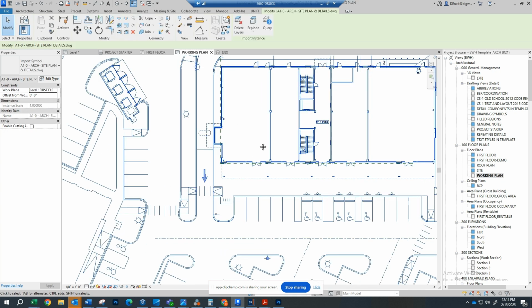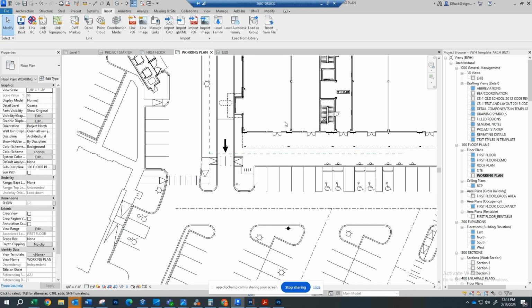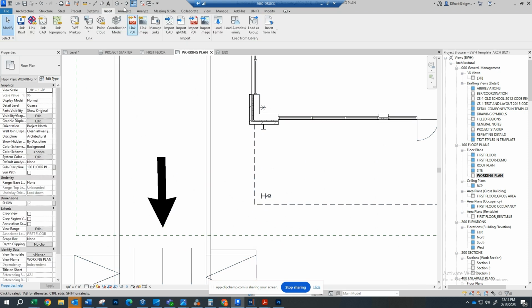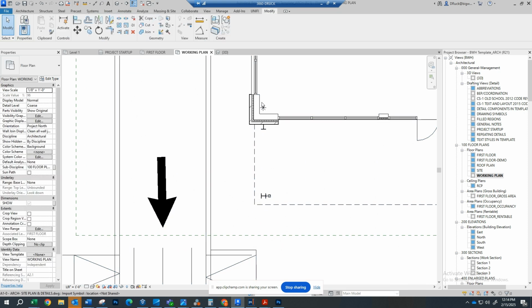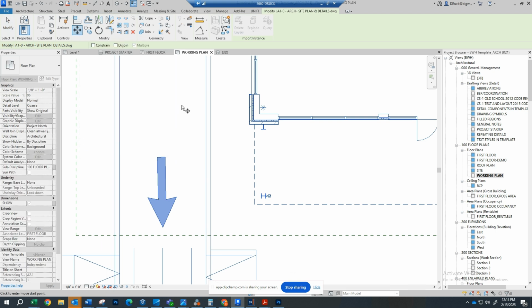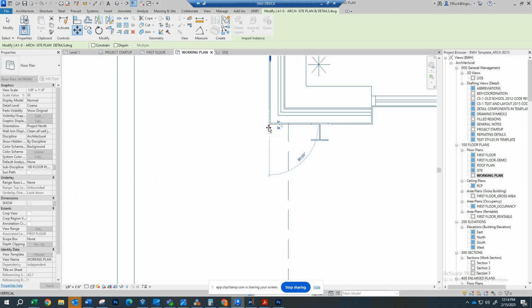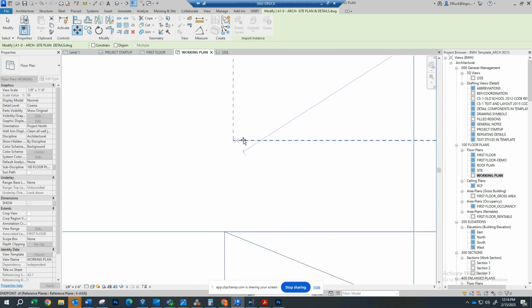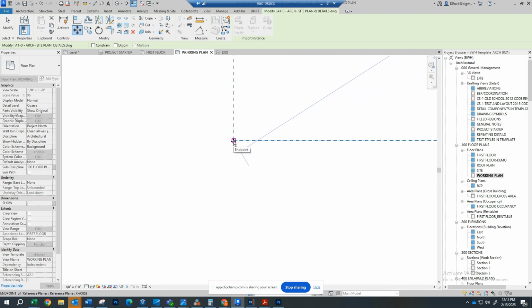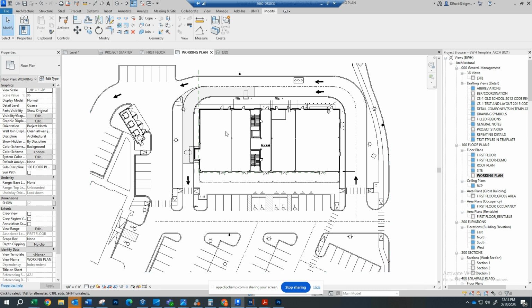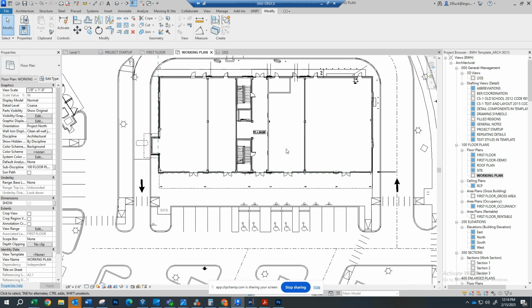Okay. So now that we have imported this CAD file, good practice or standards, you go up to the Modify tab. If you click on the CAD file that you placed and then click this Move tool or shortcut key MV, you can click it and then click on the corner. And good practice is to always start the corner of your building at the corner or intersection of the origin of the project. This way, whenever you load in a reference model or anything like that, everything will be coordinated from the same point.